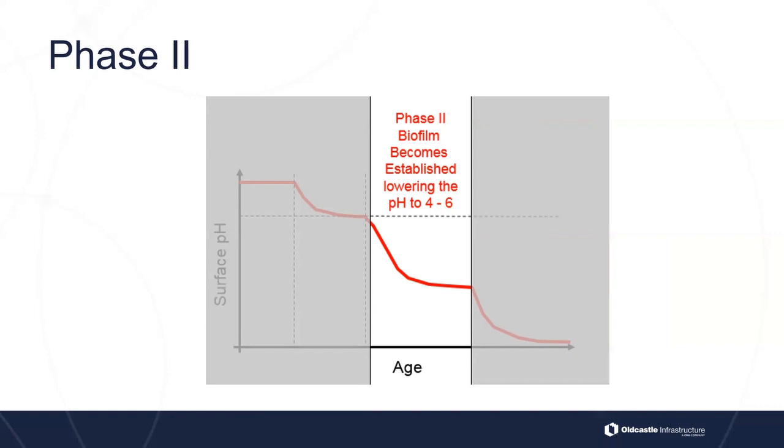So they call this the attachment phase. And that's when the biofilm attaches to the pipe. And this is where, when we're looking at the additives that we can put into the concrete, those additives can potentially take away this attachment phase so that the biofilm never actually attaches. At least that's what the theory was with these additives and what they're testing now and what we're looking at. So you've got carbonation and attachment.